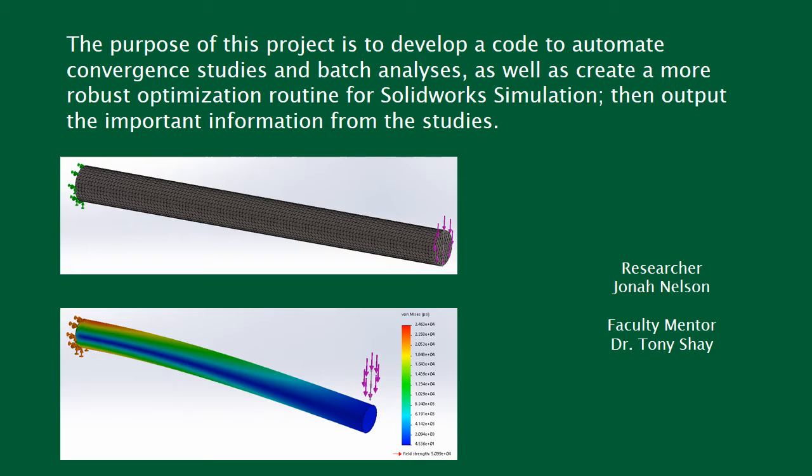For those of you who are not familiar with Solidworks, it is a CAD package similar to AutoCAD used for 3D modeling. Solidworks simulation is an FEA, or finite element analysis, plugin that allows you to perform finite element analyses. As can be seen in this top image, finite element analysis takes a model and breaks it down into many small pieces, usually on the order of a few thousand to a few million. It then takes certain constraints such as fixtures or forces and is able to find the given stress in that scenario. This is a very popular tool that is used very commonly by engineers in industry.